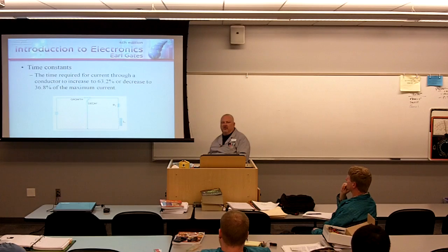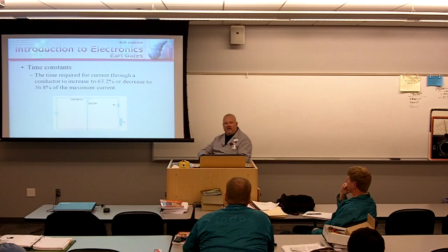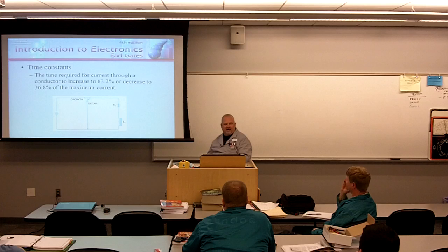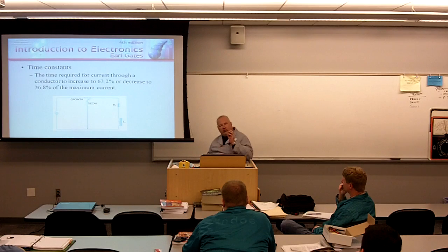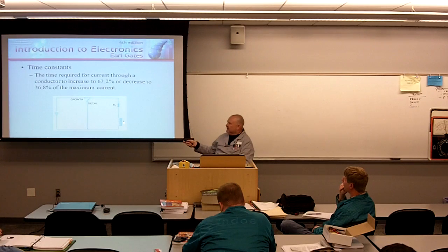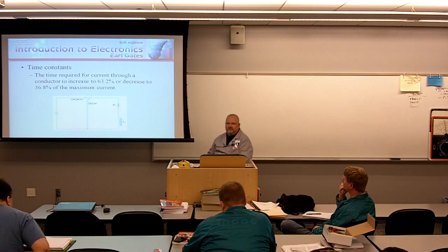It's going to act like a... What happens when a magnetic field passes through a conductor? We induce current. If we move a conductor through a magnetic field, we induce current. If the conductor is stationary and the magnetic field moves through a conductor, we're going to generate current, right? So as soon as I move this to the decay mode, this magnetic field is going to collapse into itself, creating a counter current. Lenz's law, remember, the opposite of the force that created it. And then that current is basically going to flow through the circuit until it dissipates.